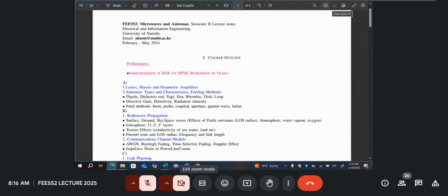Last but not least, again, there are regulations about health and safety. You could be talking about the International Commission on Non-Ionizing Radiation Protection, ICNIRP. What are the recommendations that they give? We also have CAK, Communications Authority of Kenya. How do they interpret the ICNIRP standards to CAK standards for Kenya? And what are the levels of the specific absorption rates that we expect, the maximum that we expect in the environment, so that people are not affected by this increase in temperature due to non-ionizing radiation.